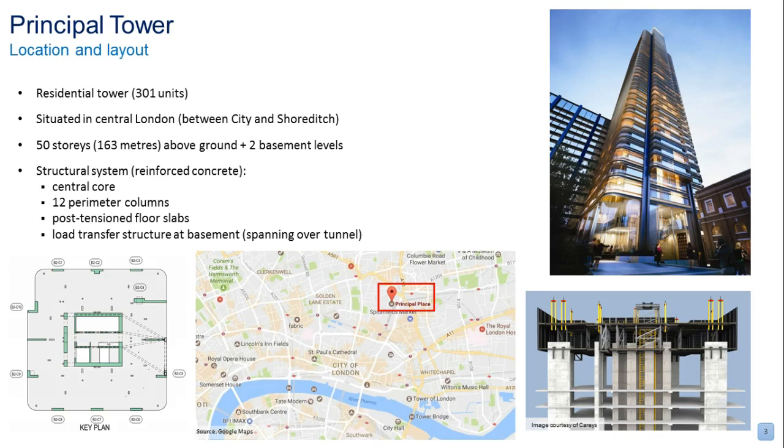However, there's a big complication when you go underground, because about a third of that building is built over a railway tunnel, which was excavated as part of the project. So that section there in red is all resting on the roof of the tunnel. The roof of the tunnel is about 1 meter thick, highly reinforced concrete, and very deep transfer beams shown in blue over there.